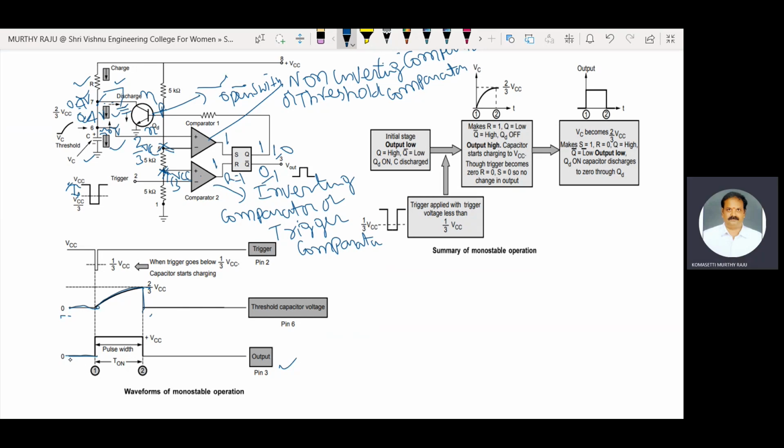Here, initially, the output is taken at pin 3. Initially, the output is low. The capacitor discharges. Trigger signal is applied. Whenever the trigger signal is below 1/3 VCC, R is equal to...